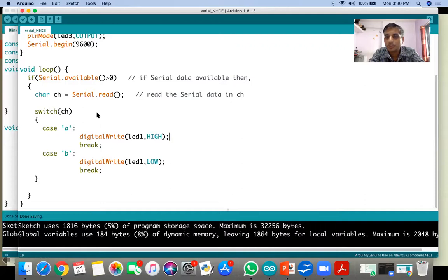Can we read a text or CSV file data residing in the computer drive using serial communication? Yes, you can read, but one program should be there in your computer which will respond to the Arduino through the serial port. That program can be designed in Java, C, C++ or even .NET.